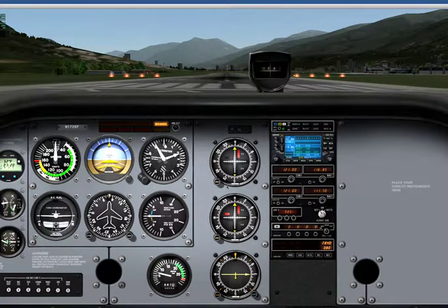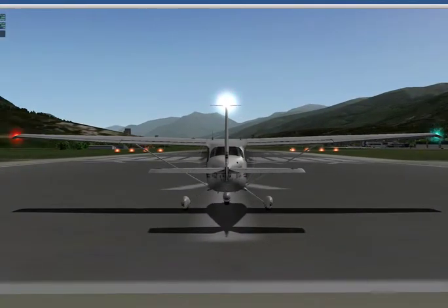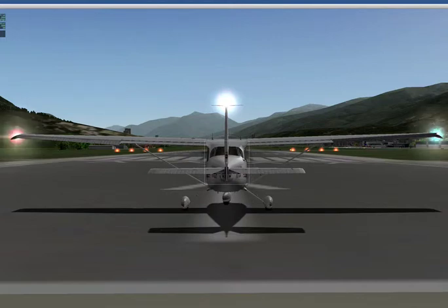All right, so what I'm saying is, if we come out in the airplane, we click here, we get this white square. Well, if I move my mouse up and down, I'm changing that back elevator. If I go left or right, I'm changing the ailerons and the rudder. And the kids can see what's going on there. That elevator is going to change the angle of attack on the airplane. You can talk about coordinated turns and adverse yaw, with those folks here that have a pretty strong piloting background.